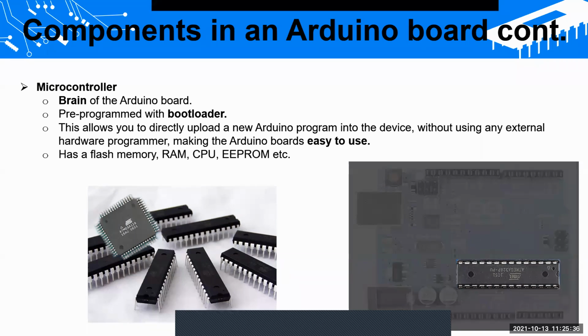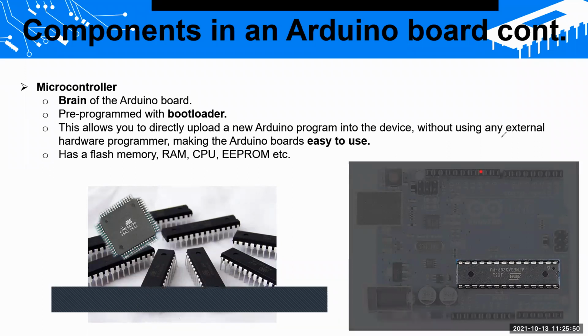Also, if you try to run a motor from your Arduino board, that will be a disaster, right? As I said before, these Arduino boards have certain limitations. You can't take around 1 ampere out of these pins. You can only get around 40 milliamperes, that is the max current you can input or output. If you need to read a current of 1 ampere, you can't do that, so for that you have to come up with another solution. We'll discuss those things in this lecture series.